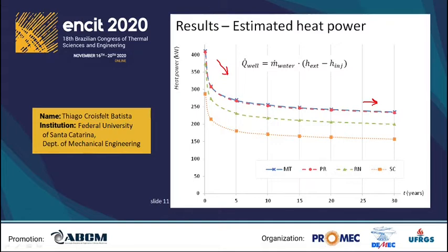In other words, the rate of geothermal heat supplied from the ground does not equate with the extracted heat power, and this phenomenon is associated with the need to drill new wells in traditional geothermal power plants from time to time. Moreover, the deepest well, this one in blue, has more area to exchange heat with the ground and the higher extracted heat rate.